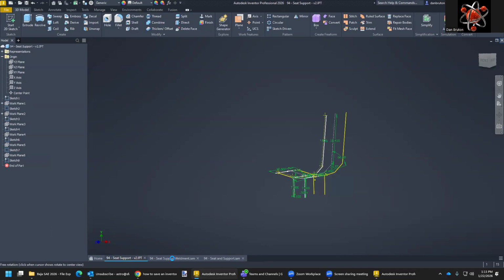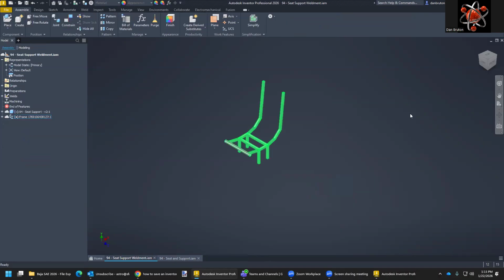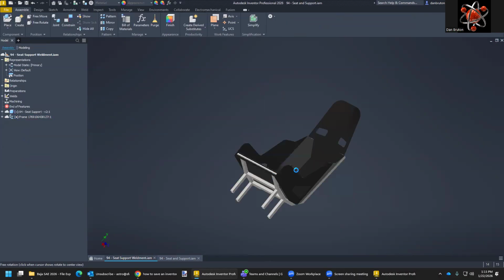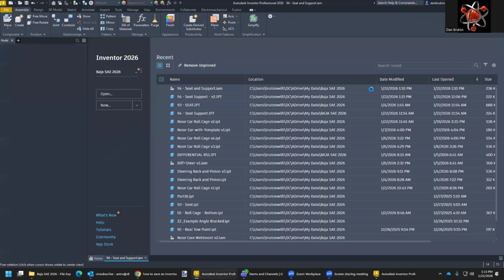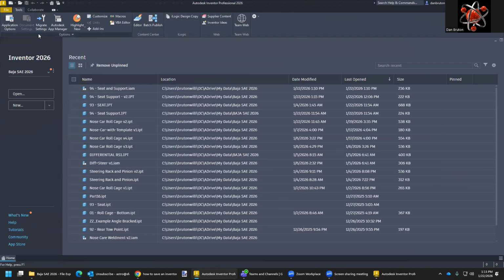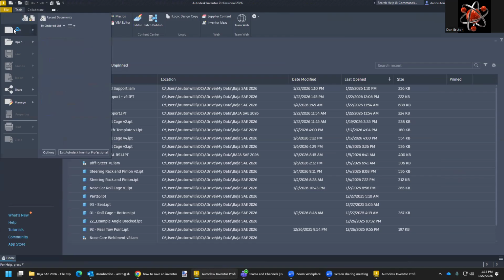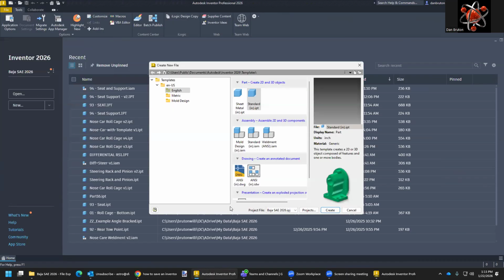It'll roll those changes forward to our weld seat support. We can close that and save any changes. And then we have this assembly, which is not perfect, but getting there. We will save it in the home position, close it out like this. So your final step will be to make a new part file and just pull in the assembly as follows. So new part file. That's the only kind of file that I can read when you put it in D2L. Otherwise, I have to kind of figure out where all of your pieces are and put them together.